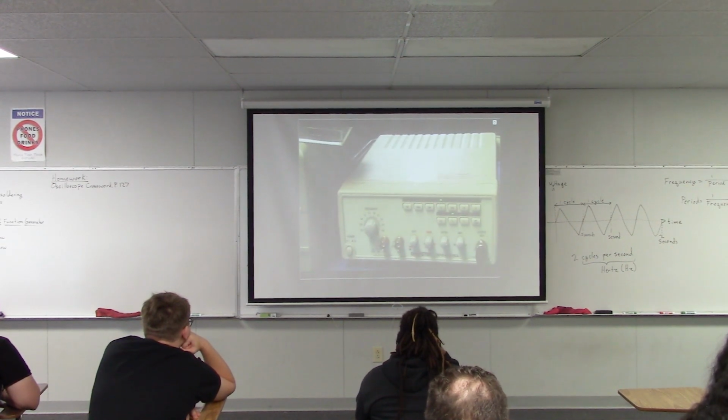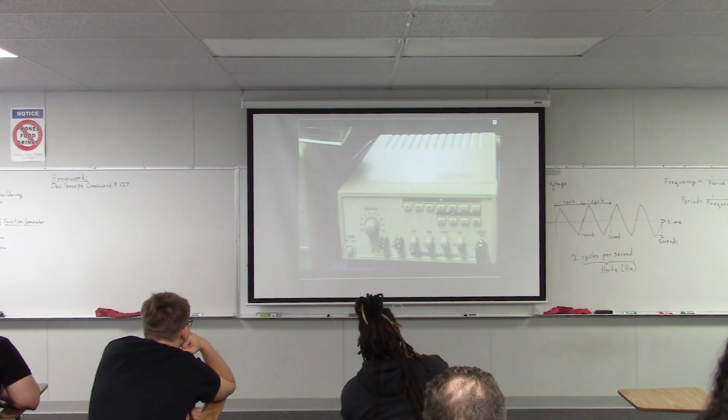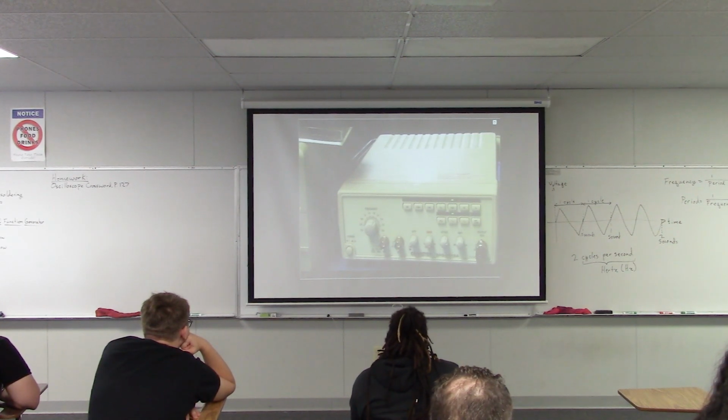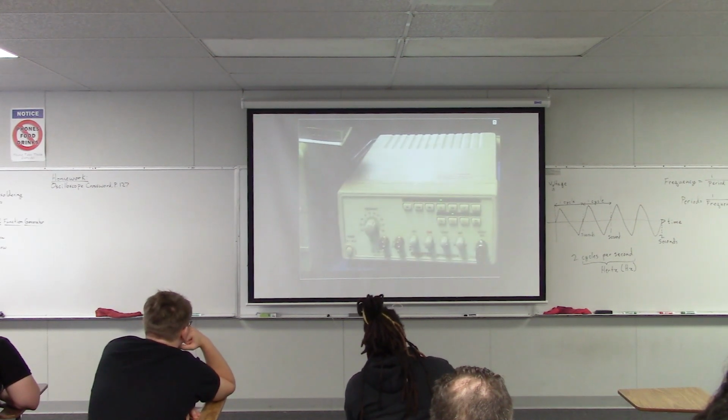So what's our approximate frequency? 1,500. Yeah, about 1,500 hertz. 1,000 times 1.5 is 1,500. If I move that and put us in the 100 hertz range, what would be our frequency now? 150, exactly. And if I put it down at the 10 hertz range, we'd be at 15 hertz. So that's how you actually set the frequency. You set the range, and then you multiply it by the number on the frequency knob.